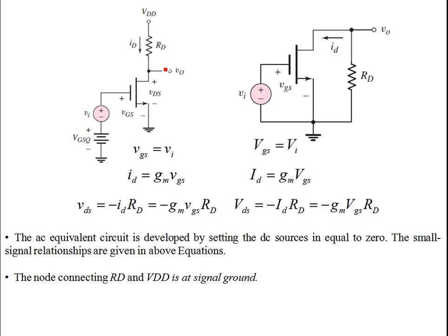If you compare this DC circuit with the NMOS device, over here you see the direction of the current is into the drain. Okay, and you have VDS over here. You're still taking the output from the drain, but the current is going into the drain and out of the source. That's the conventional way of giving the current direction for an NMOS device, and the voltage polarity is VDS. Similarly, you have VGS, where the gate is at positive potential and source is at the lower potential.